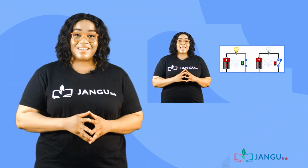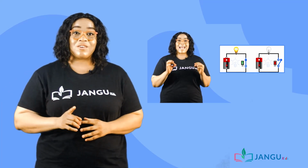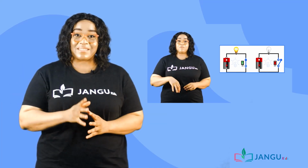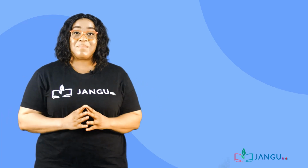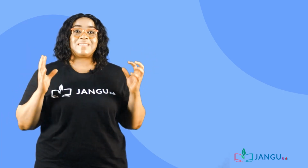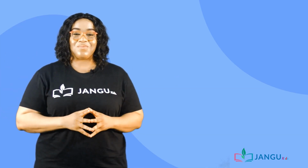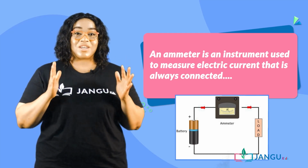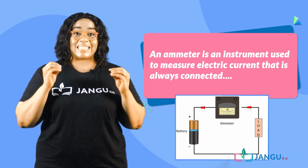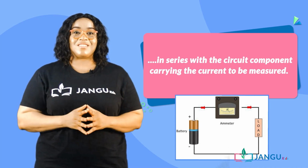In our previous lesson, we learned about the direction of electron flow in a circuit and how to set up series and parallel circuits. Moving on, let's take a look at how we can connect an ammeter or a voltmeter to a series or parallel circuit and read their value. An ammeter is an instrument used to measure electric current that is always connected in series with the circuit component carrying the current to be measured.